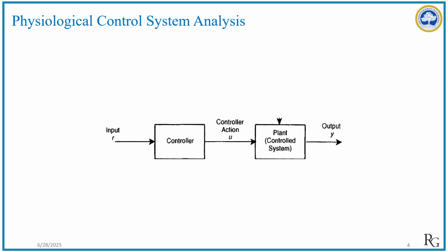In an open loop control system, we have one controller which generates the control action, and there will be one plant or system whose output has to be controlled, but there is no feedback. So in this type of system we don't know whether the desired output has been achieved or not. In ideal conditions, if we configure the input as per the requirement of the desired output, the system works well. But in a general scenario or in an actual control system problem, there will always be some disturbances, which can be generated from inside the system or from outside of the system.